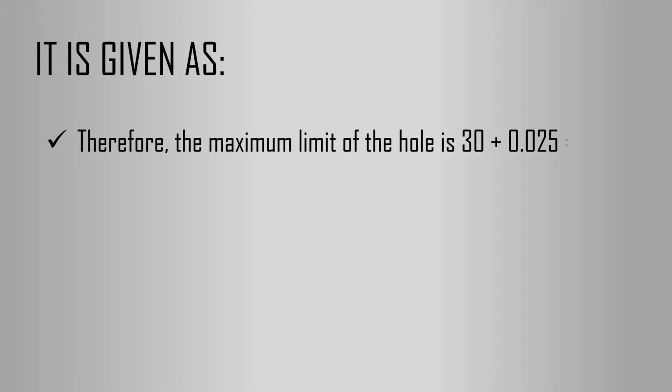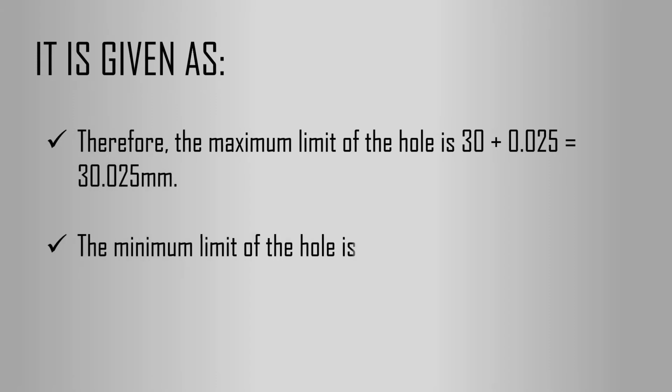It is given as. Therefore, the maximum limit of the hole is 30 plus 0.025 is equal to 30.025 mm. The minimum limit of the hole is 30 plus 0.000 is equal to 30.000 millimeters.